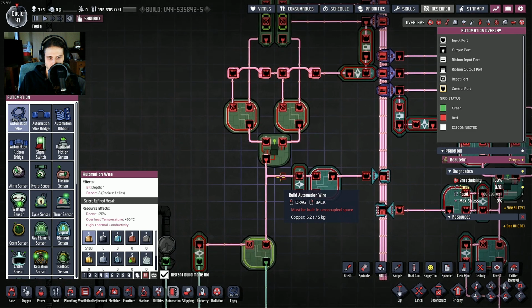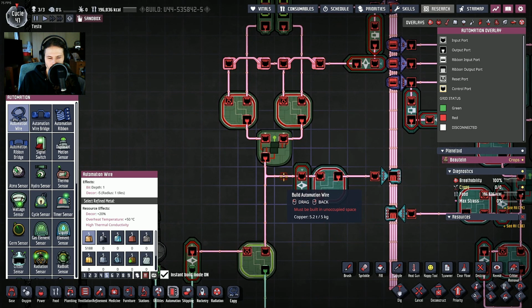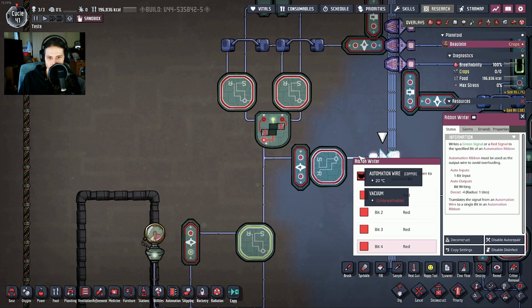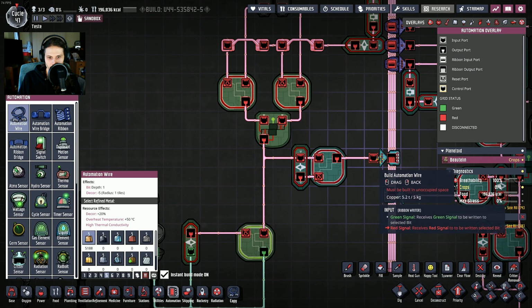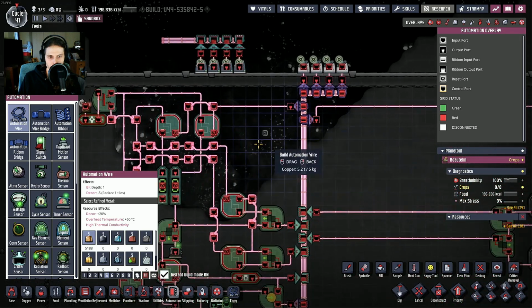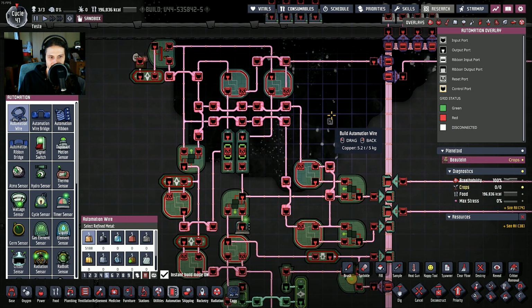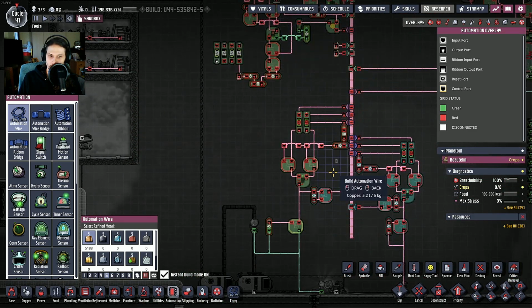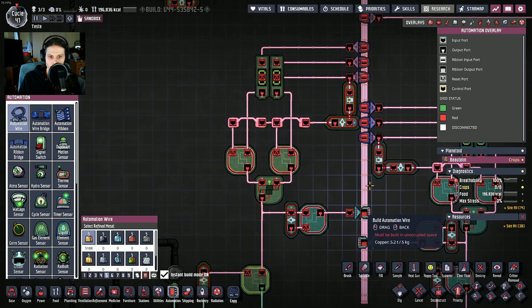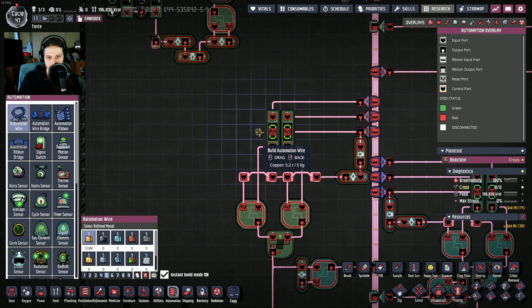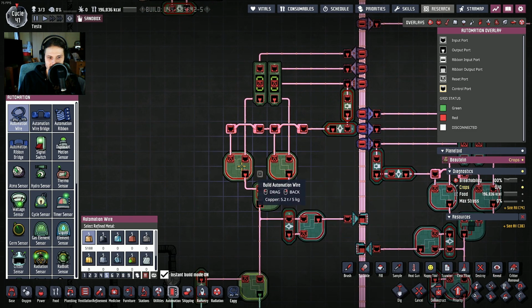Right. Then over here we have a confirmation pulse. That's why we have this pulse generator right here. This pulse generator will generate a small pulse into bit 4, which will confirm to the encoder that the message was received and will reset the entire thing back to 0. Not only that, it will also reset the counters over here back to 0 and these over here back to 0.